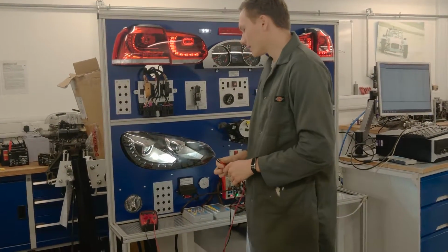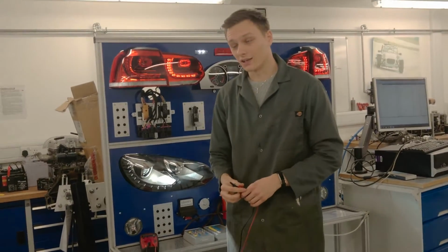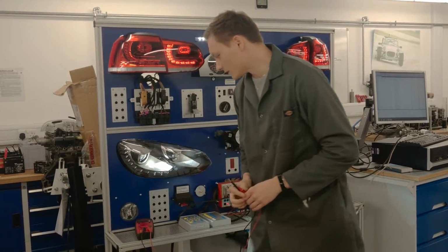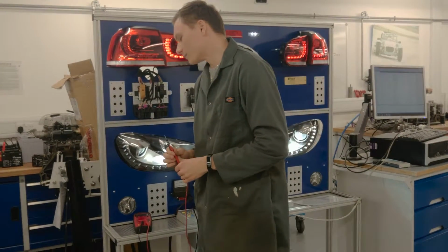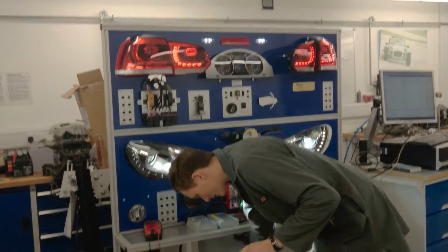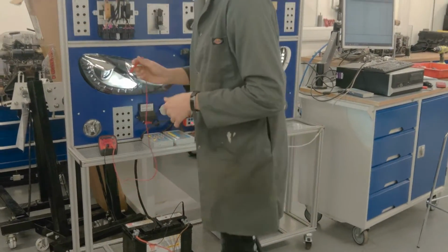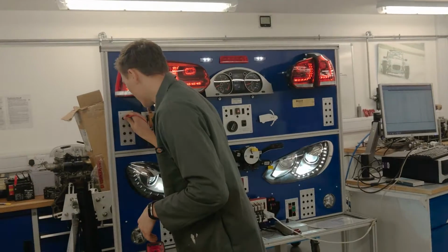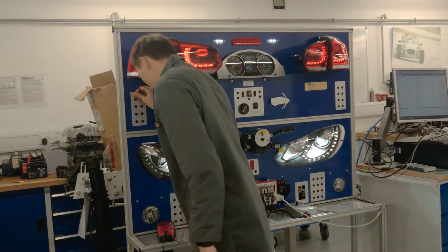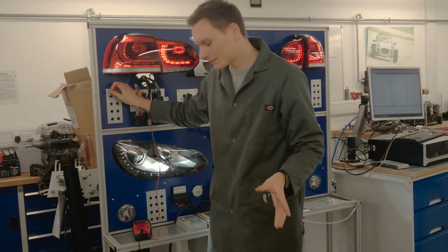So for the open circuit, the other test we can do is the continuity check. So if I switch the multimeter to continuity check, if I put once again black wire to the ground and red wire to module 21 of the brake light system, and there is no beeping sound.